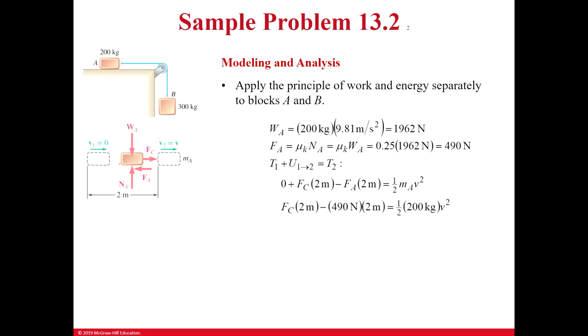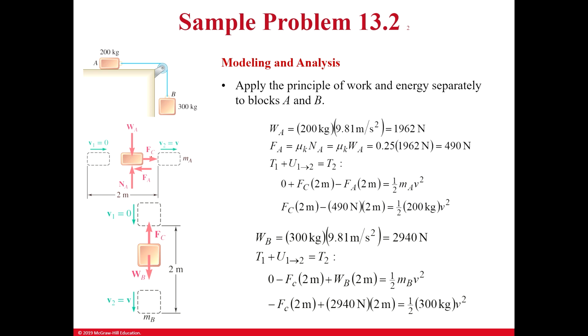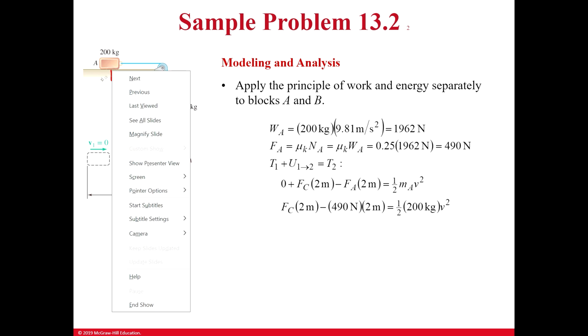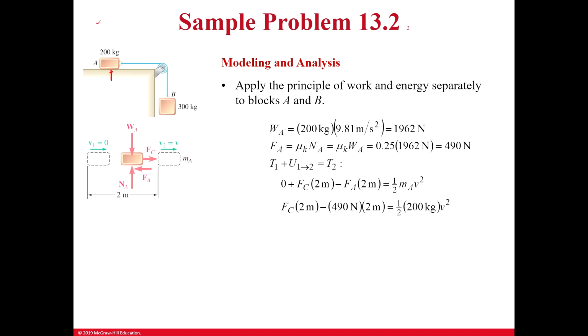Let's start with block A. In block A, we have the normal force, which is going to be very useful because we have a coefficient of friction. Remember, the coefficient of friction at A is 0.25. It's pretty high, so it has a lot of friction.